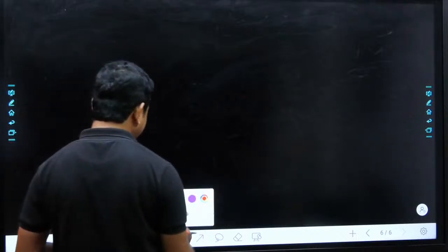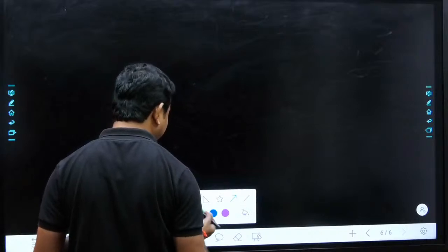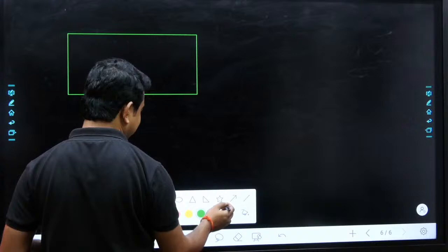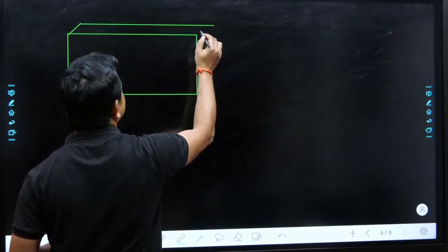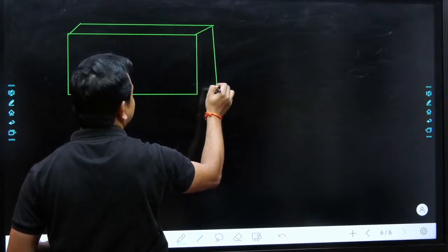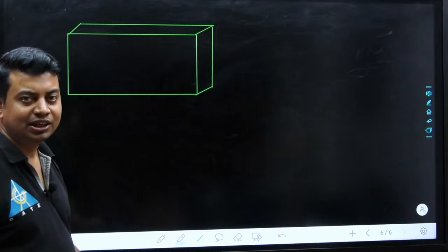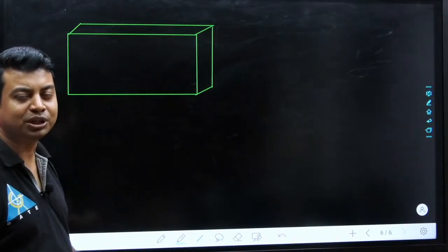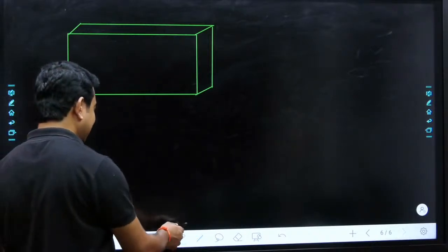So, we are having a p-type semiconductor. How can we construct a p-type semiconductor with non-uniform doping? Suppose this is a semiconductor and it is a p-type semiconductor with non-uniform doping. Here we have drawn each and every point because I haven't given an idea about the cross section. Cross section is always taken in the direction perpendicular to the direction of movement of charge carriers or direction of current. So, this is the cross sectional area.